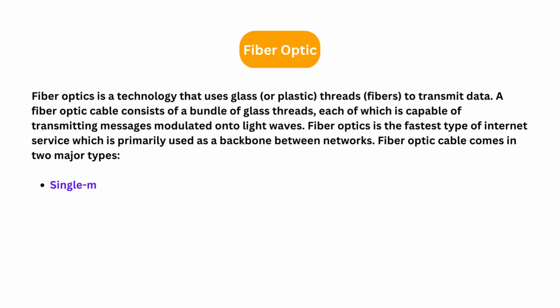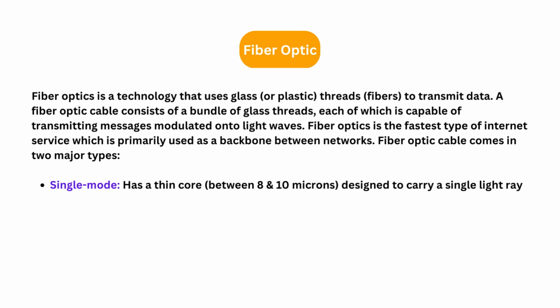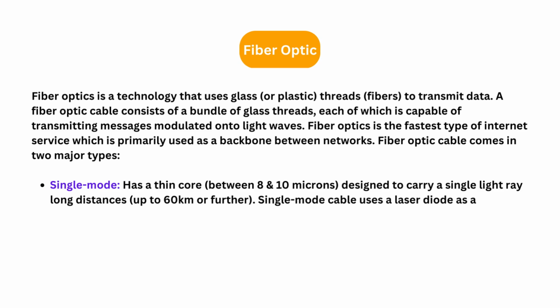Single mode has a thin core, between 8 and 10 microns, designed to carry a single light ray long distances, up to 60 kilometers or further. Single mode cable uses a laser diode as a light source. Typical uses include cable TV and telephone companies.